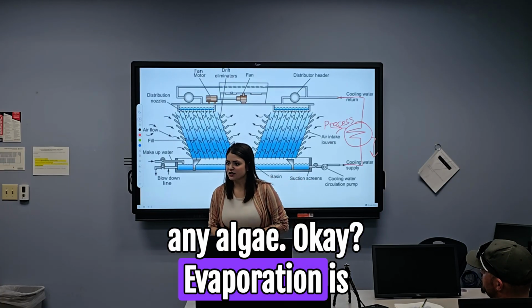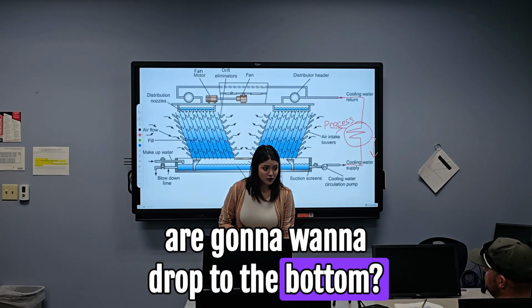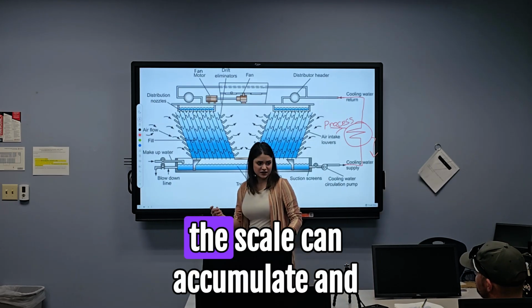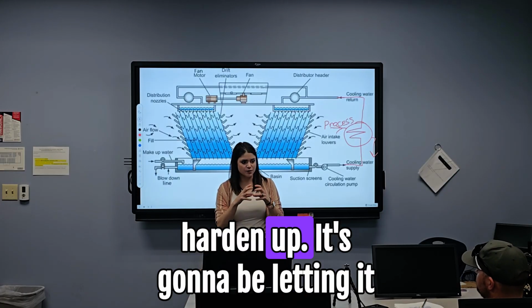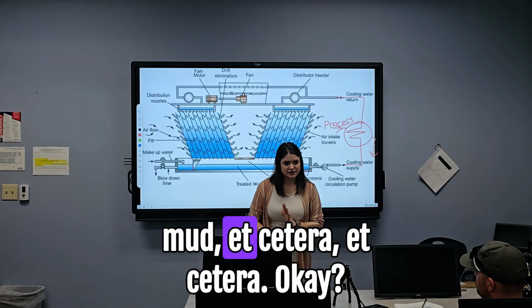Evaporation is happening. You think our heavy minerals in our water are going to want to drop to the bottom and cause scale. So before the scale can accumulate and harden up, we let it come out the bottom: algae, dirt, mud, etc.